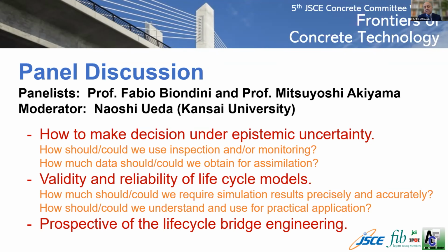And this is appropriate in many cases, but sometimes when the diffusion process is governed by 2D or 3D gradients of concentration, it is necessary to use more complex models. This depends on the type of structural members affected by diffusion. The type of cross-section, for example, is very different if you have a solid rectangular cross-section or a hollow core cross-section. You have different exposure for the reinforcing steel bars. For example, for bars that are far away from the corners, perhaps a 1D solution is appropriate and sufficiently accurate, but for bars in the corners, it is not.